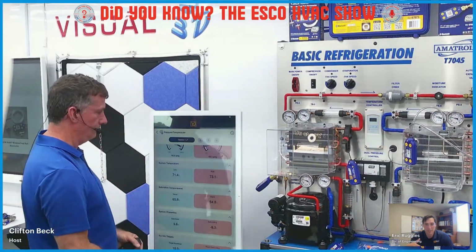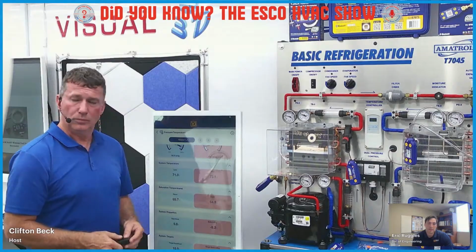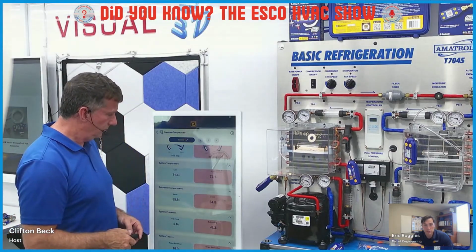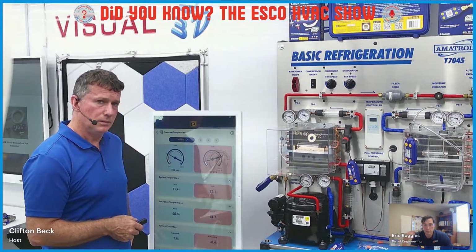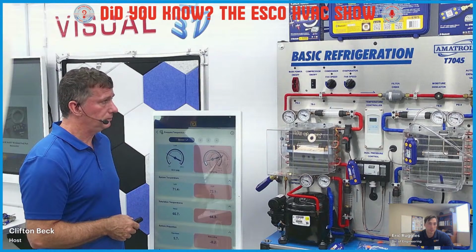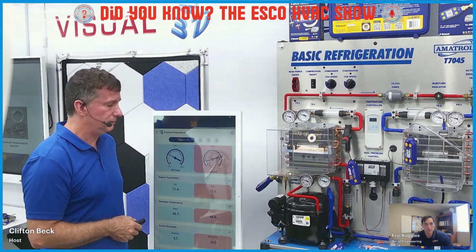Report, multiple sections, and you can add sections from there, and then that's how it goes. But yeah, it'll take a snapshot of the current readings if you're just in the session. If it's doing a test, like a vacuum test or a leak test, or picking an anemometer session with different airflow readings, duct traverse, it'll spit out the reports. When the test is done, it'll ask you if you want to add it to a report. Then you can add those results.